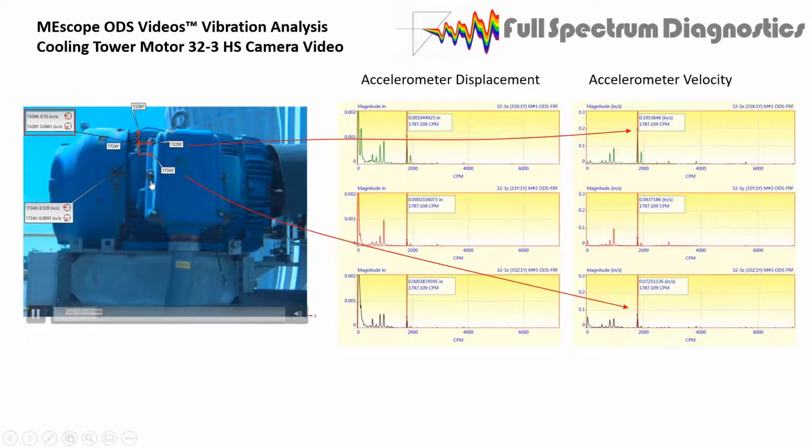And if I have the correct measurement, like the length of the stator or the diameter of the bell housing or the nameplate, the correct dimensions, if I get a good dimensional value for that, I'm going to get good data that's comparable to the accelerometer data.